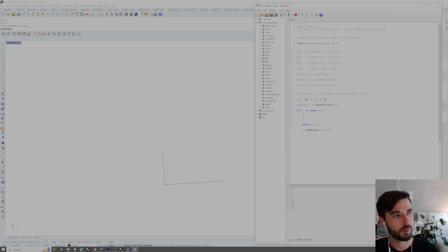So I'm going to uncomment both the points list and the polyline. The polyline we want after we've already iterated through all of these points. So I'm going to delete those points, and we can just move this polyline by cutting and then pasting it somewhere after our for i in range loop. Right now, we're still just reading these 3 points that we've commented out, so they don't exist. So we have nothing in this list, just an empty set of points.